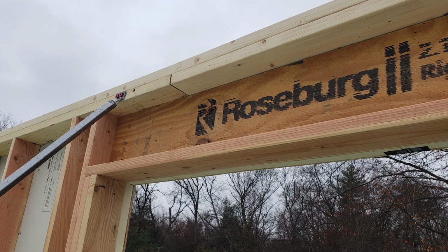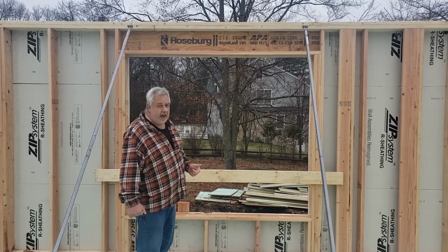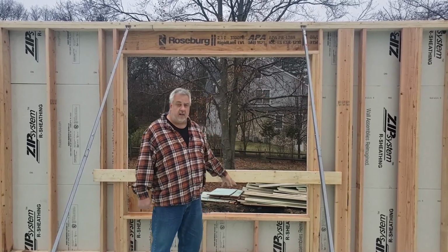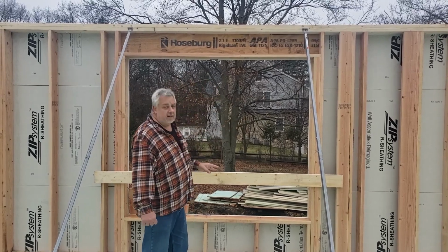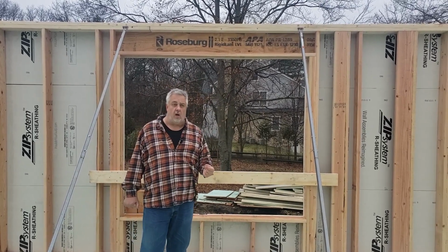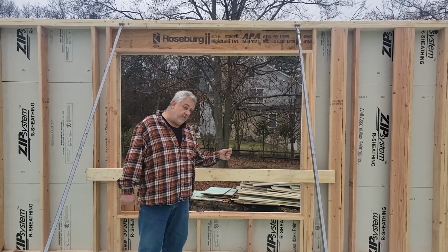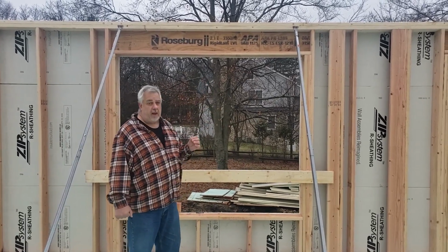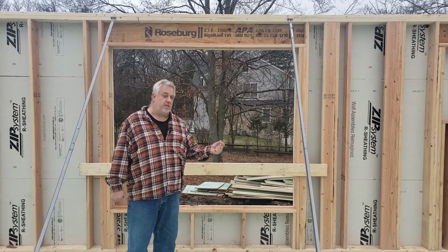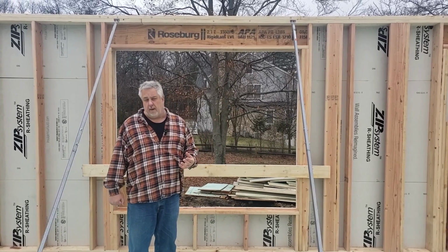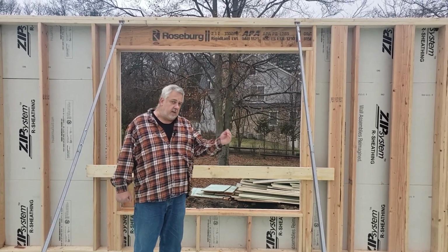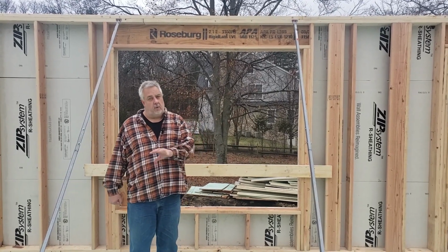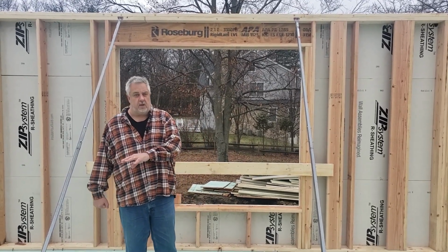But the beauty of that is because I have that pocket, it allows the insulator, when they come to insulate the wall, to simply insulate that pocket as another wall cavity. As well, when the framers are framing the wall, they're just doing their thing without adding any extra components and rigid insulation and built up headers or any of that. So basically the framer does what the framer does when it's time for him to do it, and the insulator gets to do what the insulator does when it's time for them to do it.